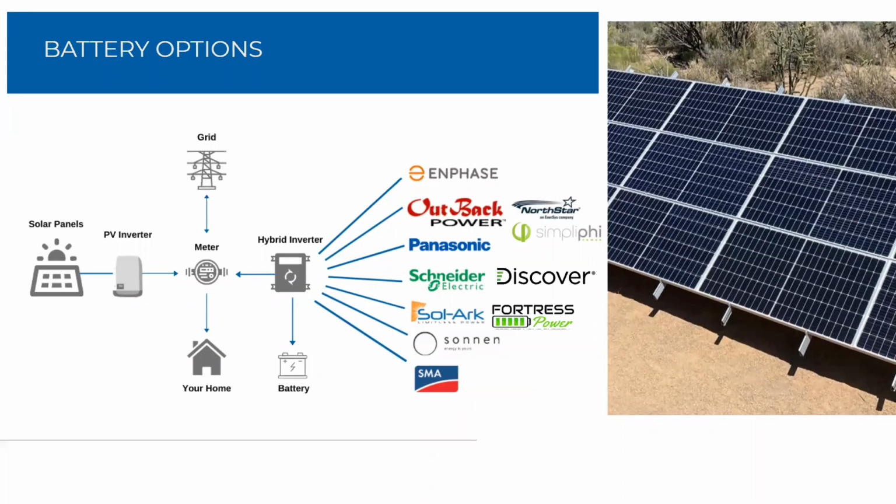So I think to be cautious, you could size it based on a few of these medium-sized appliances running simultaneously. But if you're educating the homeowners enough to say, listen, all of this is capable of running, but none of it should be running at the same time, that's really the biggest hurdle, making sure everything isn't running at the same time.